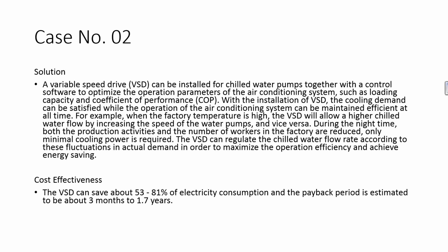The cost effectiveness: the VSD can save about 53 to 81% electricity consumption, and the payback period is estimated to be from about 3 months to 2 years.